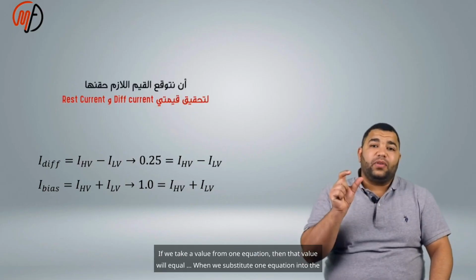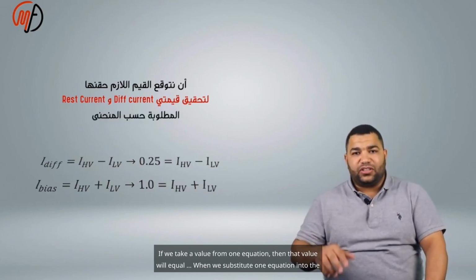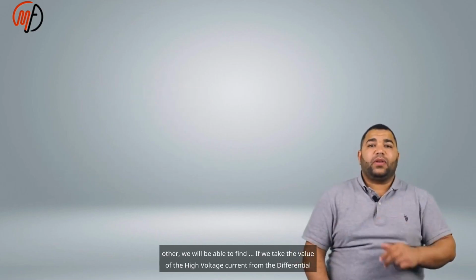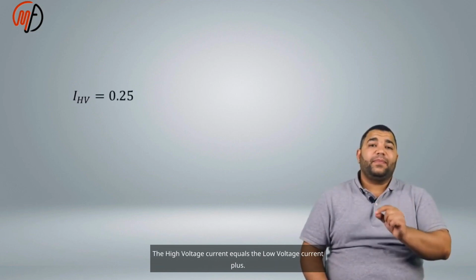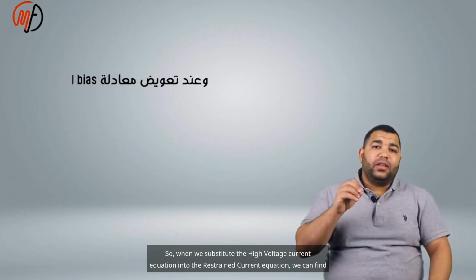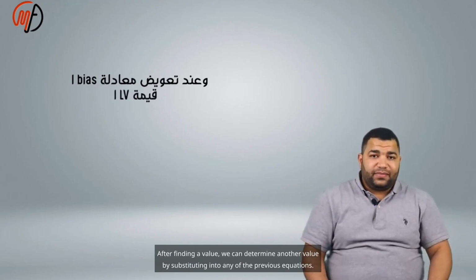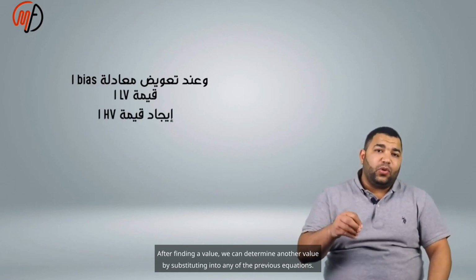If we take a value from one equation, then when we substitute one equation into the other, we will be able to find the values. If we take the value of the high voltage current from the differential current equation, then the high voltage current equals the low voltage current plus the differential current. When we substitute the high voltage current equation into the restraint current equation, we can find the low voltage current. After finding one value, we can determine another value by substituting into any of the previous equations.